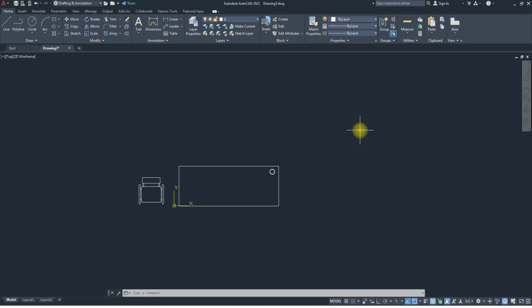Remember in tool palettes, when we were inserting blocks from tool palettes, we got to electrical. And when we inserted the electrical components, it brought out one dialog box that talked about block attributes, where you have attributes to that block. It was because those electrical components were created using attributed blocks. They added attributes to them. That's why with these blocks that I created, inserting them didn't bring anything. We just inserted and that was it. So we can actually create a block such that anytime you insert it, it brings up a dialog box and tells us to fill in some settings.